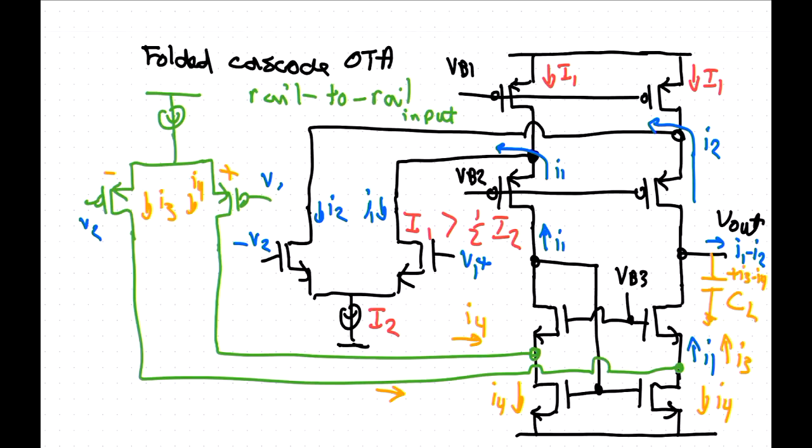And then you have either a feed forward or feedback system that makes sure that the sum of the two currents is constant over the entire range. So when you're at mid-rail where they're both turned on, you just wind down the current in both of these two, for instance. There are many things that we can't talk about.